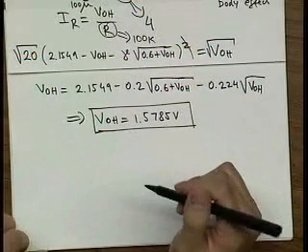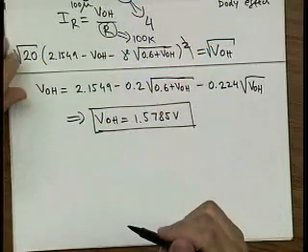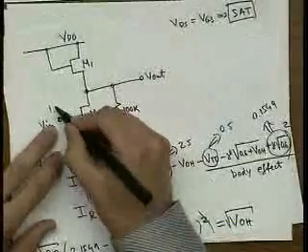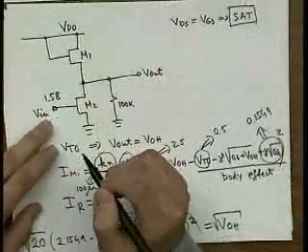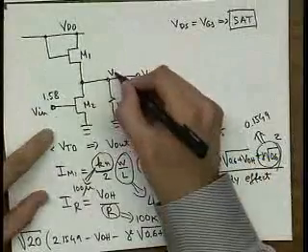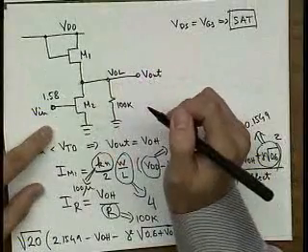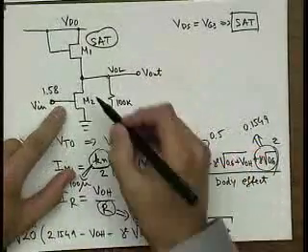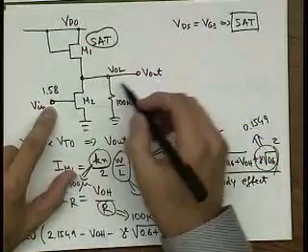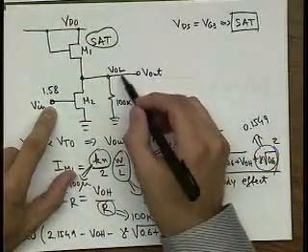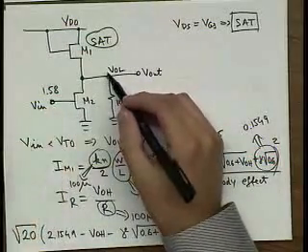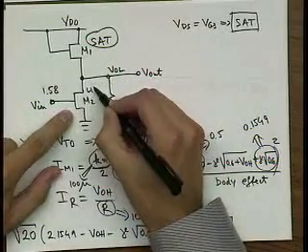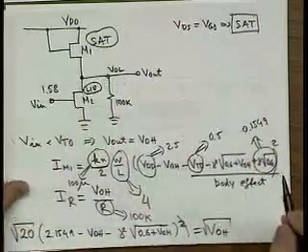Let's do that. So before we do that, we first need to figure out the mode of operation for our transistors. So now let's assume that this is 1.58, that's VOH, and this output over here is VOL. So this one is always in saturation, so no question about that. And then since this one is sufficiently high, and assuming that VOL is less than VT, because that's the best assumption we have so far, it follows that this one would be in the linear regime over here.